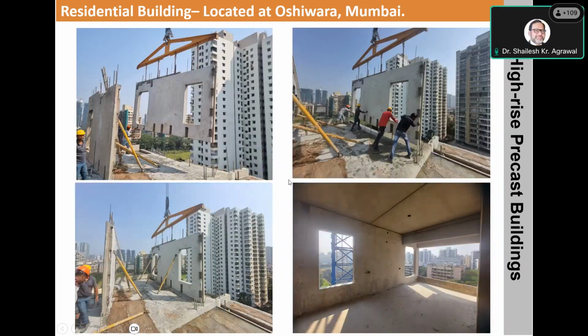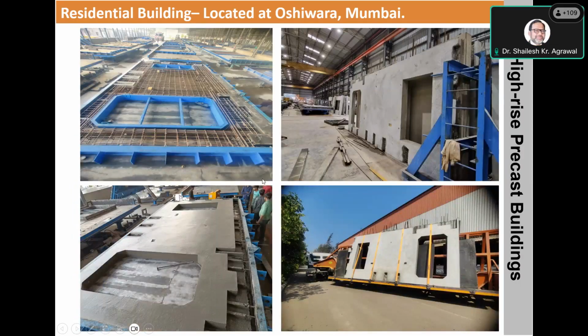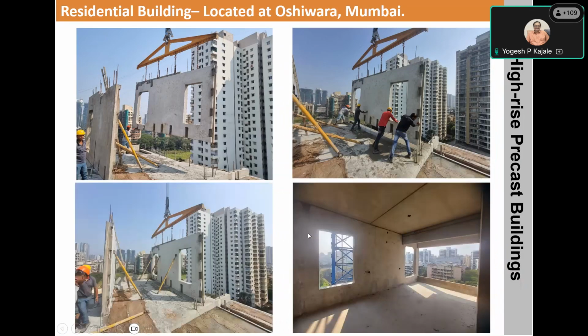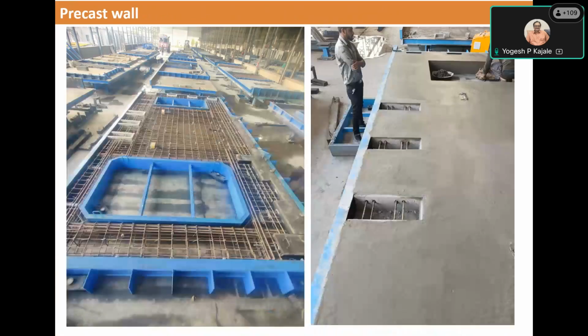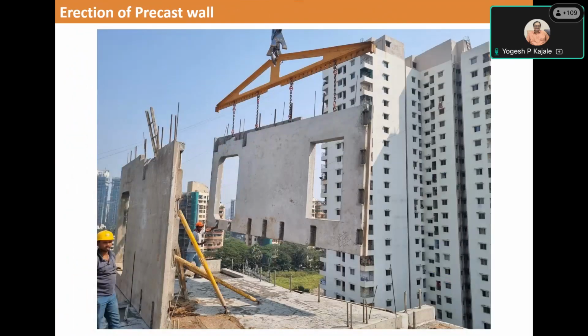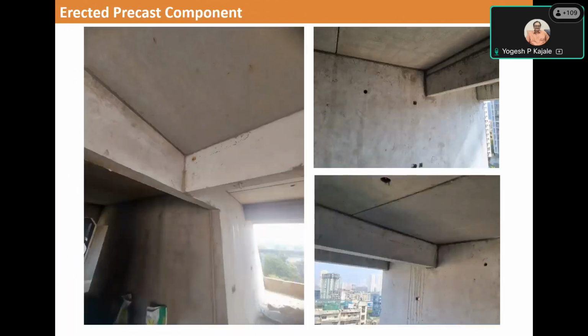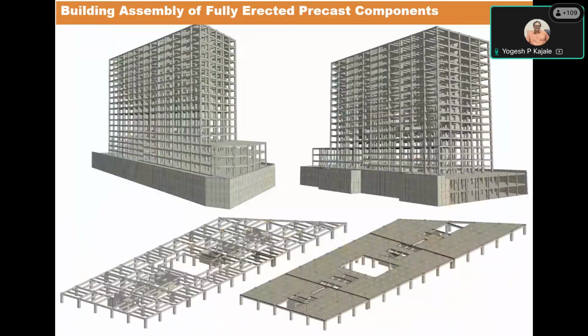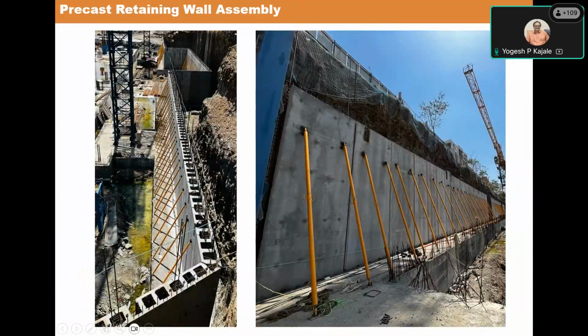Next is how waterproofing is done at joints, particularly at basement retaining walls. In our basement retaining wall, we use the hollow core elements. The two hollow core elements have a half core, particularly at the joint. On the left side, you can see these cores are full, but on the bottommost part, there is one open core.